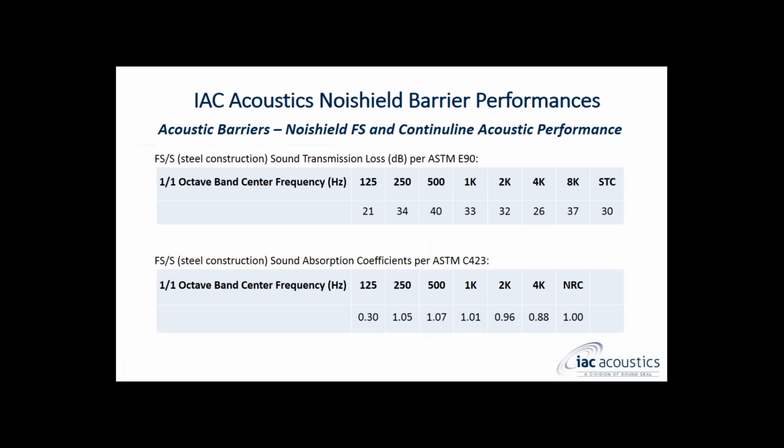And what we do is simply report the lab data that's present. So if you look at the sound absorption coefficients on this screen, at the 250 and 500 hertz and 1 kilohertz octave bands, you do see numbers that are higher than 1. In practice, those numbers would be limited for calculations to less than 1.